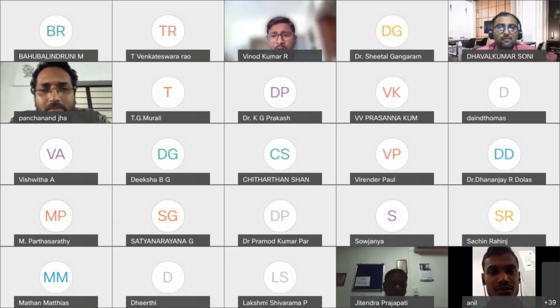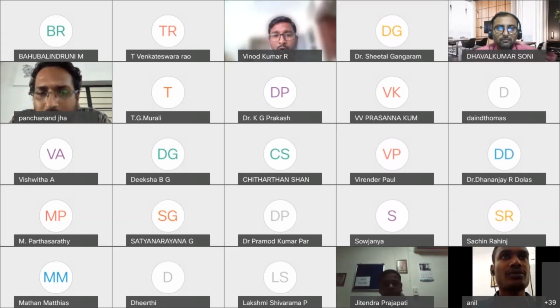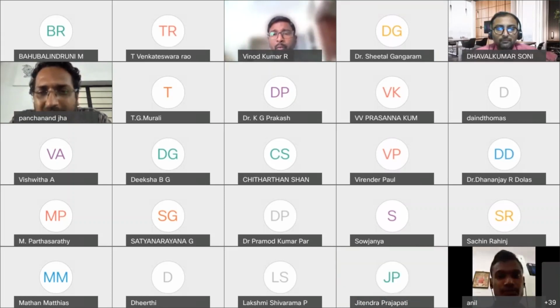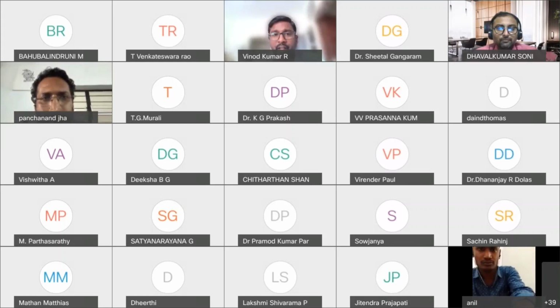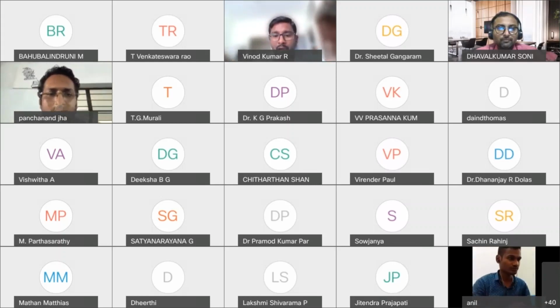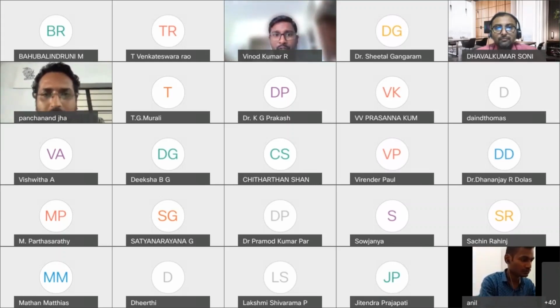But for this particular location, the robot we have used already has 40 micron positional accuracy, so we don't require an additional vision sensor. We might require one in a case where a carton box is coming onto the conveyor and we don't know which face is in the right direction or not. In that case, we can go for a vision sensor.